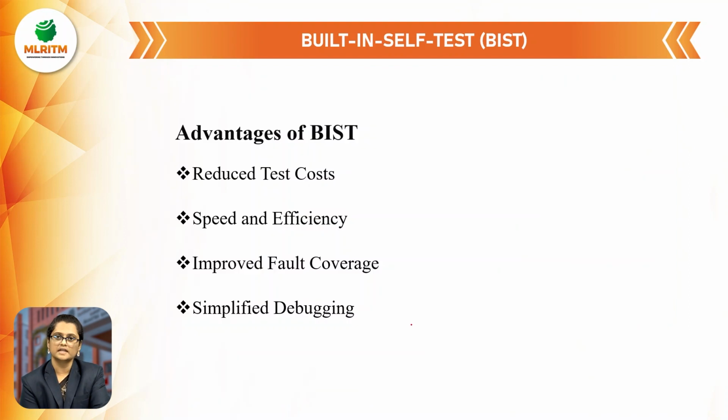And coming to the advantages of BIST, we already discussed it previously. It reduces the cost compared to the ATE, gives speed and efficiency improvements, improves the fault coverage, and simplifies the debugging concept.